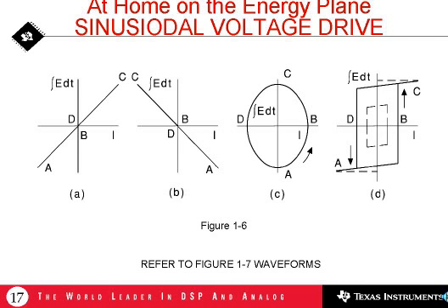And it turns out that some of these metals used for metal alloy tape-wound cores do have very high permeability. Molypermalloy has a relative permeability of maybe 100,000, nearly vertical as seen on a display such as this. Ultimately, that characteristic saturates, and so you see at the top and the bottom some moderate slope. That is the finite slope when the material saturates.